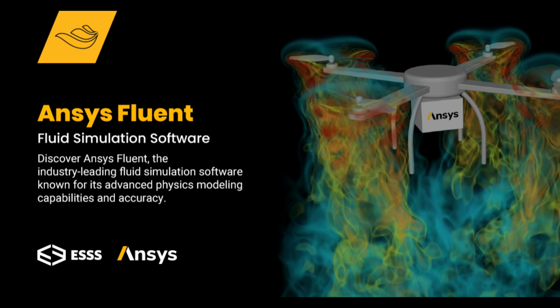So what are the basic fundamentals of CFD? CFD is based on three main fundamentals. First, governing equations of physics. This covers the continuity equations, Navier-Stokes equations, and the energy equations for the heat and temperature effects. And for the mathematics, numerics, we have the discretization method. The physical geometry is divided into small cells called a mesh, and the equations are solved numerically at each cell. Common numerical methods are the finite volume method, finite element method, and finite difference method.